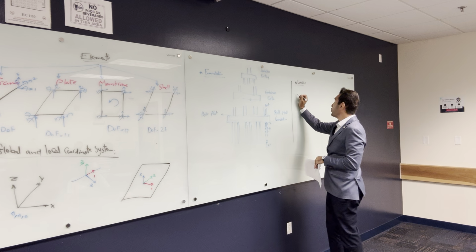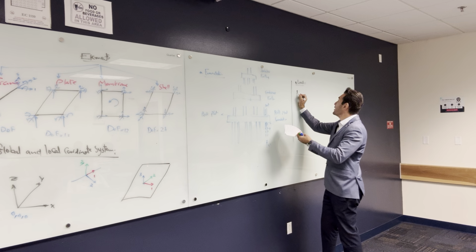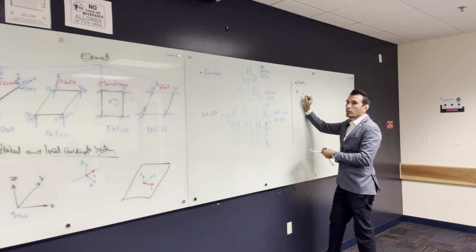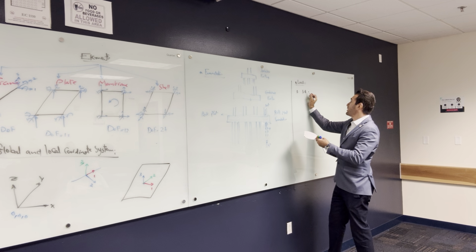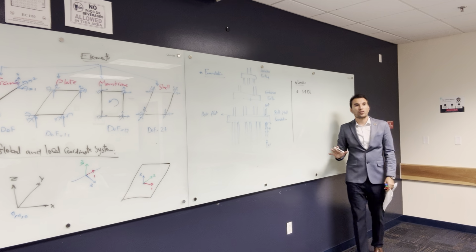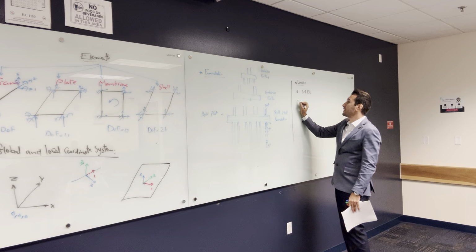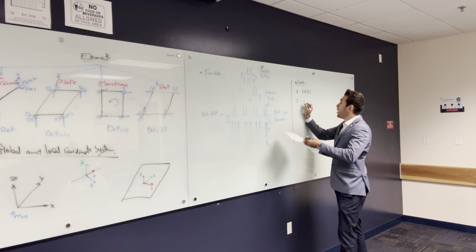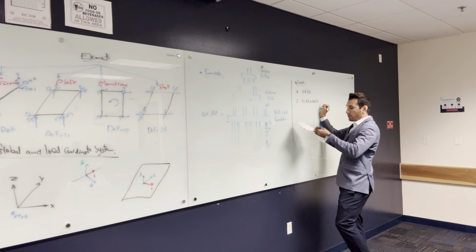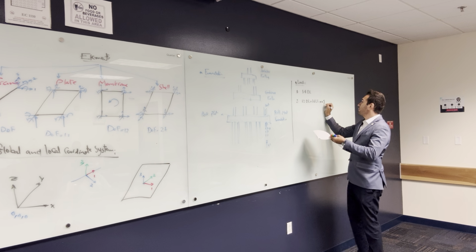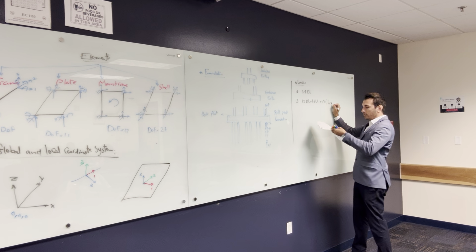If you go to chapter 2 in the ASCE 7-22, you will find some of these load combinations. The first load combination that you need to design your structure for is 1.4 dead load. You assume this structure doesn't have any live load, and it has 1.4 dead load. The second load combination is 1.2 dead load plus 1.6 live load plus 0.5 any roof load.